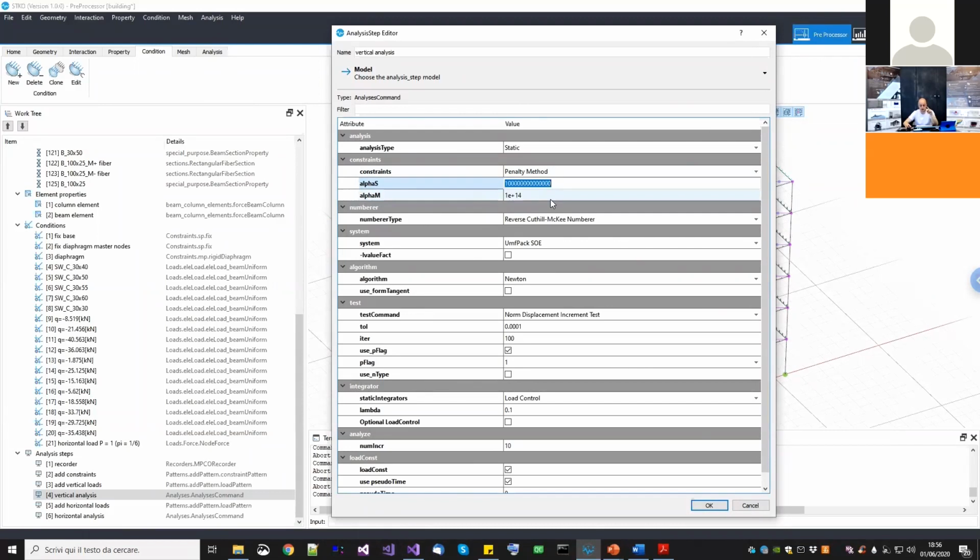One extra thing we are working on now in OpenSees is something that can basically automatically compute this value for you, because we understand that computing the penalty parameter is not so easy for people that are not experts with the finite element method. So we are going to create an automatism in OpenSees to compute this value for you. So everything else is fine.